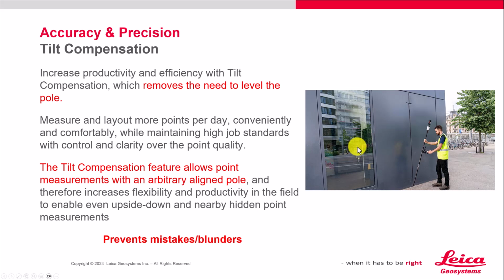Tilt compensation removes the need to level the pole. The tilt compensation feature allows point measurements with an arbitrarily aligned pole, or you can hold it level and it sort of proves whether or not you held it level. But again, it prevents mistakes and blunders.